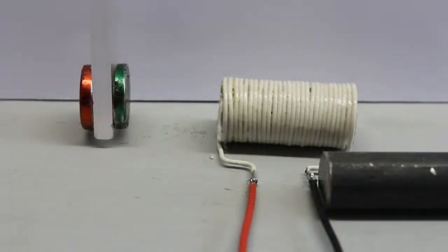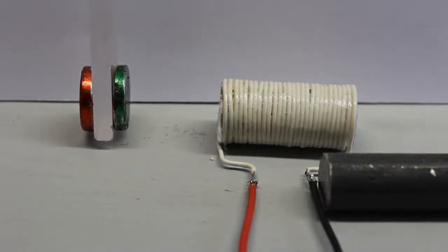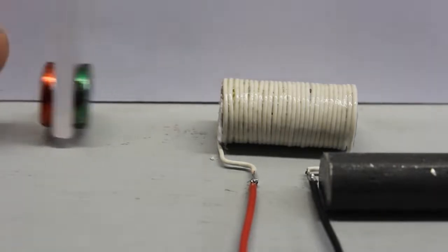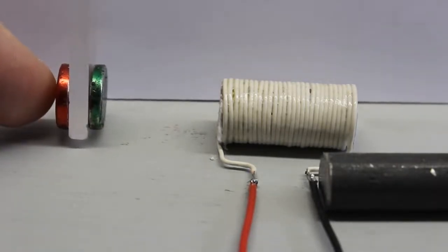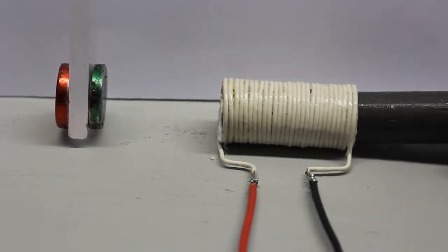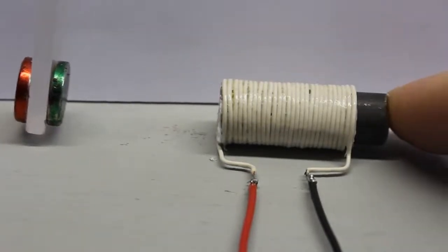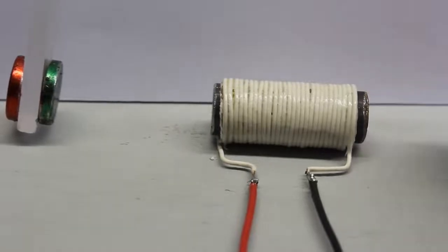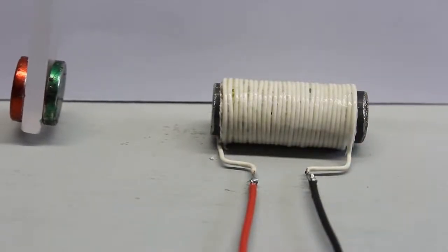Coils of a DC motor are usually wrapped around an iron core. Iron concentrates the magnetic field at the ends of an electromagnet. That means the forces acting between electromagnet and permanent magnet are raised by the iron core. However, there is no need for an iron core to make a DC motor work, as we will see some later in this video.